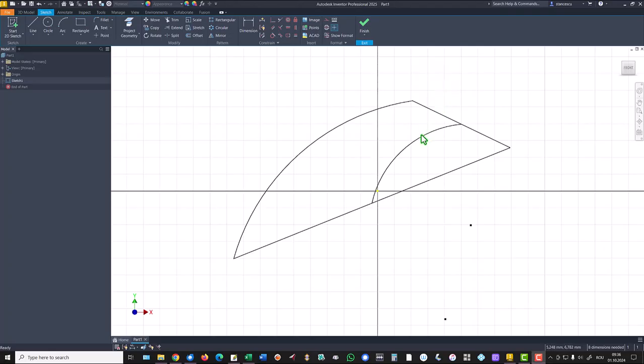If you want to select one entity, you click on it. You know this. But if you want to select more than one entity, you can use this window, click here, keep pressed the left button and go here. And you selected these two entities because they were inside that rectangle. You can also select entities from right to left, not left to right. You see, this is another presentation. And go here. You've selected all the entities intersected and included by the sides of that rectangle.